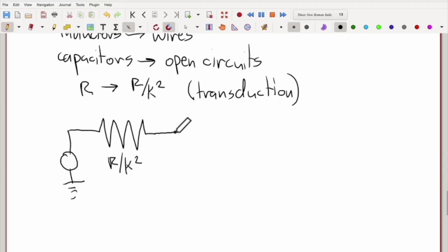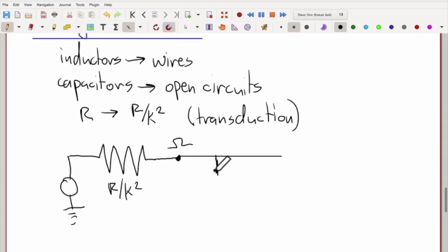And now we have our node here, which has angular velocity omega and the torque Tm coming through here. And then it's connected to these sources of drag here. We've left out the rotor inertia, which looks like a capacitor, because it becomes an open circuit, so we don't have the inertia appearing here.